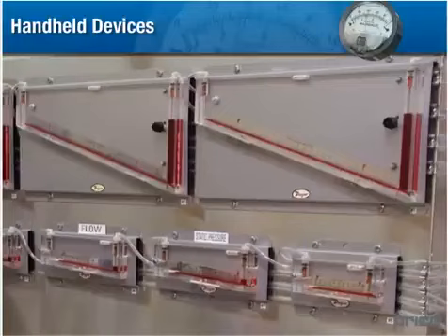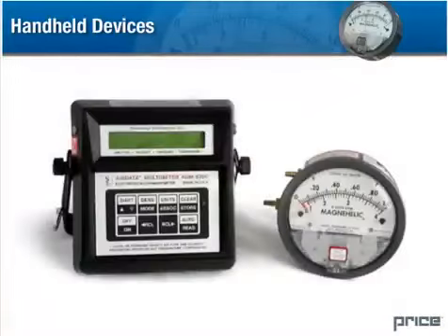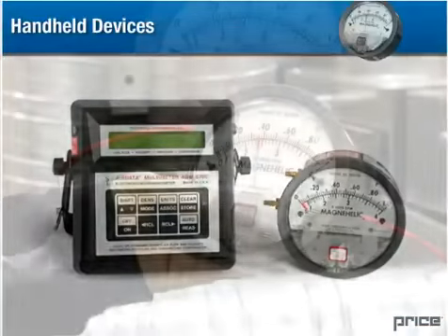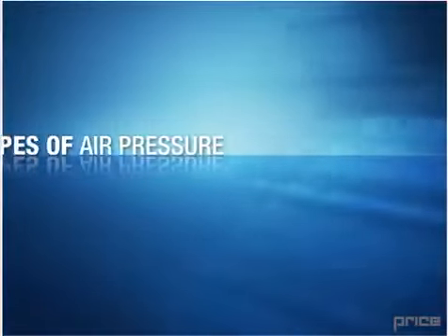While the manometer may seem a little low-tech, it provides highly reliable, precise, and reproducible measurements. However, due to its size and delicate construction, it may not be the instrument of choice in field testing. Handheld pressure measurement units, such as those shown, might be used instead to calibrate and evaluate HVAC systems in the field. Types of air pressure.